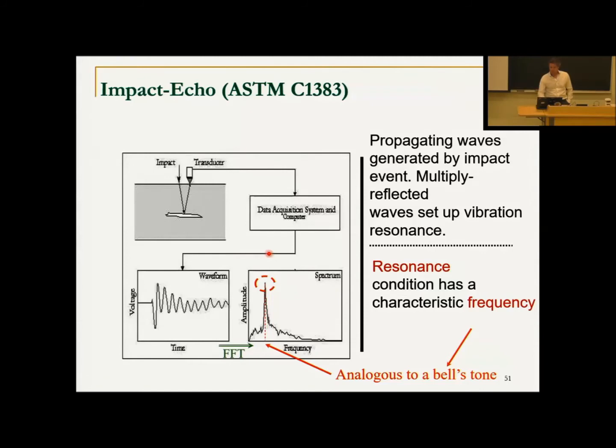as before, and instead of just having an inspector listen for sound, actually measure the motion, the vibration that results, capture that and quantify it in terms of frequency content or other things. So for example, here we have an element and we tap it, and instead of listening, we put a sensor that measures motion, and we measure this wave motion output. We can see here voltage over time. This is the A scan, right? And maybe that will tell us that's how we quantify the sounding.